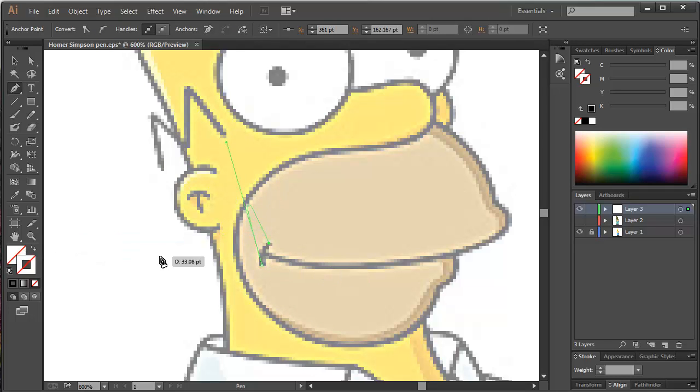Okay, now I'm not showing anything here as far as my line, so I'm going to come here. My fill should be none, so you can click on fill and click this if there is a fill. And then stroke, you should have a stroke, so you can click on stroke, and then down here on your stroke panel, just click 1 or 2, however thick you want it. So I'm going to do 1 for now. I can always change it later.